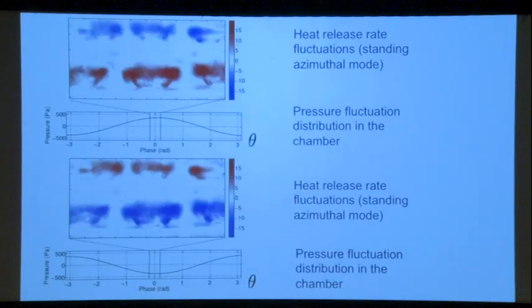All right, so we've done that analysis. We see that the pressure is in phase with the heat release rate fluctuations in a standing mode in this case, and the pressure fluctuations, you see, they are in phase.